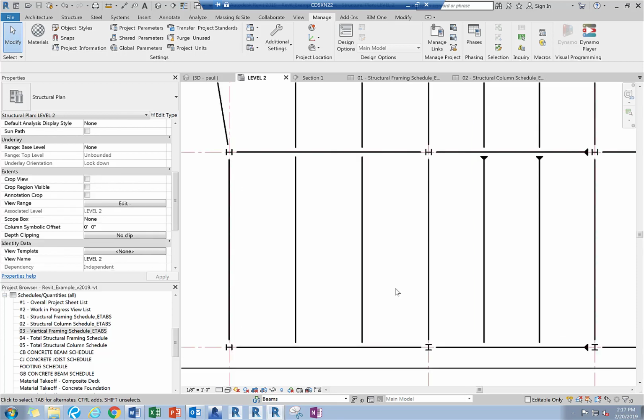After each floor is modeled, run the flip beam direction arrow Dynamo script to view if any of the beam geometry is not connected. This will require you to put the beams on the beams workset one level at a time initially to ensure that there are no discontinuities between your geometry. A generic model will be created for you to identify any discontinuities between your geometry.